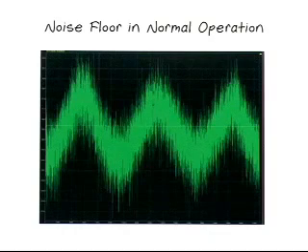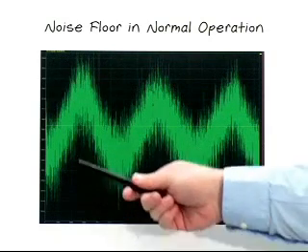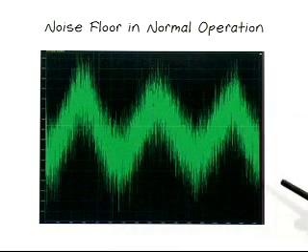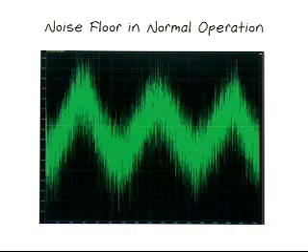Now I would like to show how digital feedback can manifest itself in the noise floor of an ADC. Here is a magnified screenshot that shows the noise floor of the LTC2261. Digital feedback typically produces a shaping of the noise floor as shown. In this case, the digital feedback causes peaks in the noise floor of about 3 dB. The layout of the LTC2261 demo board was optimized to minimize digital feedback, but still some is unavoidable. In applications where poor layout is used, these peaks can be up to 20 dB.